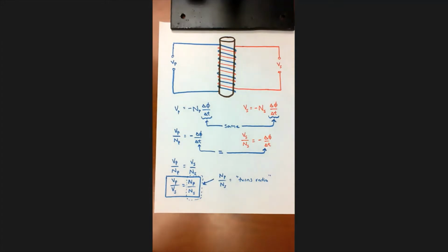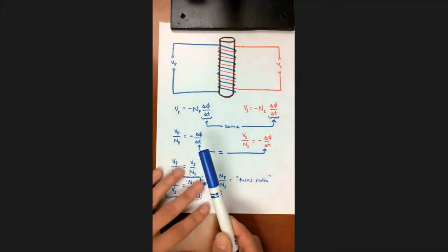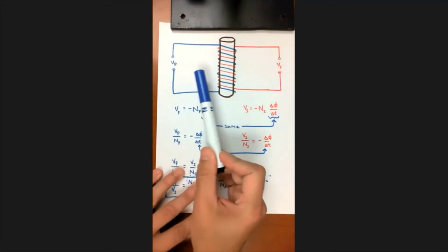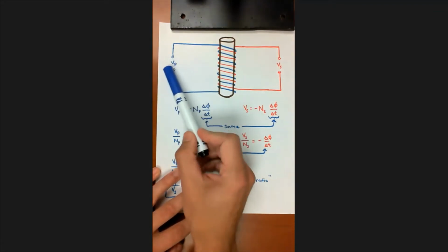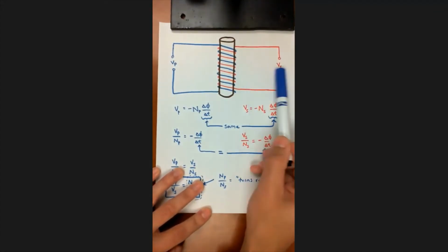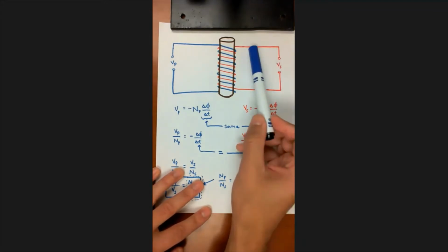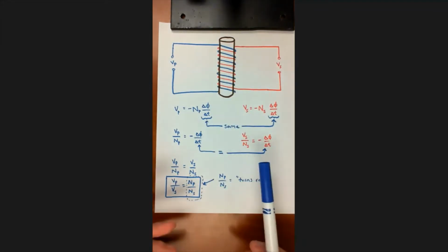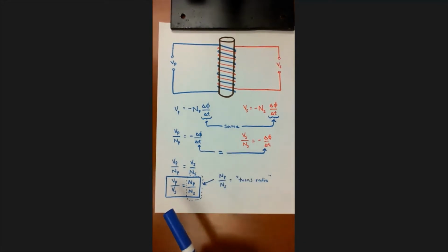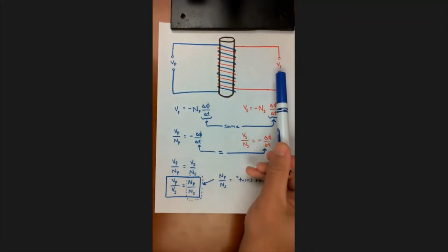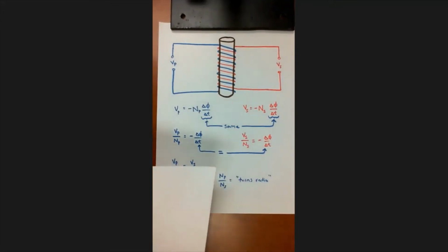The other important thing that we can recognize, and it's a bit of an assumption, but a pretty decent one, is that the power that we apply to the transformer through the primary windings is equal to the power we're going to get out of the transformer via the secondary windings. In other words, power is conserved. We can say that this transformer is 100% efficient, which of course is an assumption, but not a terrible one. Most transformers are on the order of 97, 98, or 99% efficient in terms of the output power divided by the input power. So it's a decent assumption.